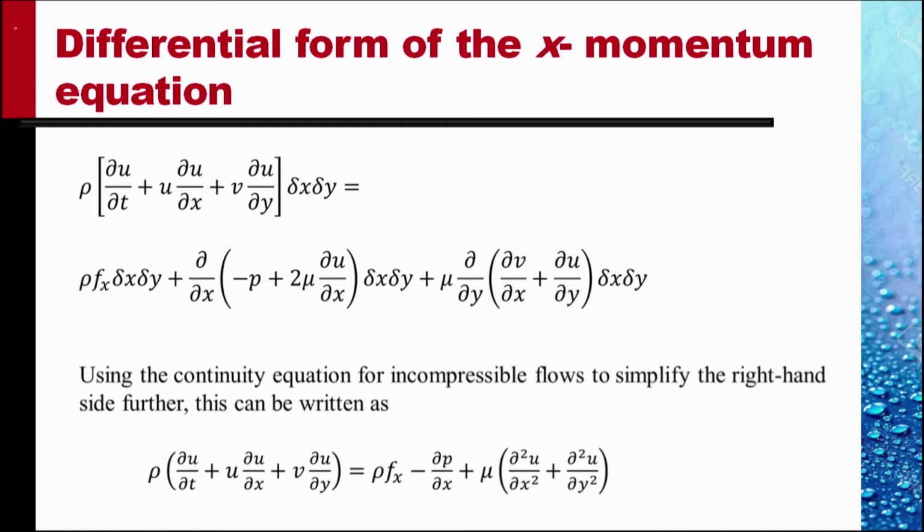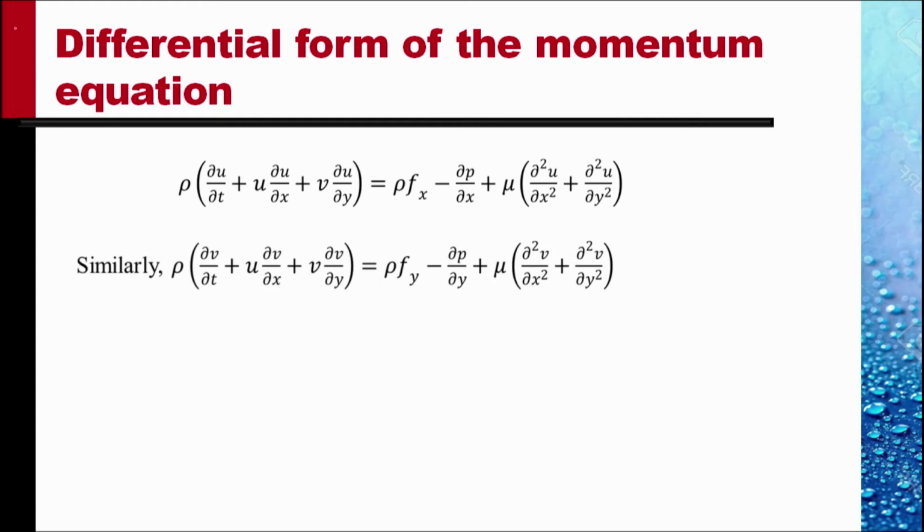We can similarly obtain the equation in the y direction, and the only difference would be that u would be replaced by v, fx, the body force in the x direction, would be replaced by fy, and del p by del x by del p by del y.